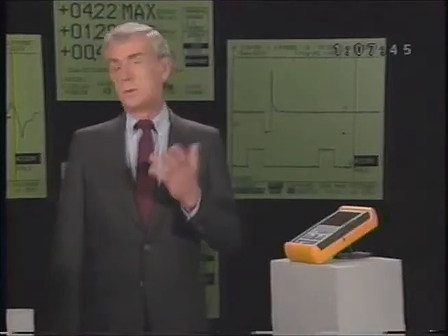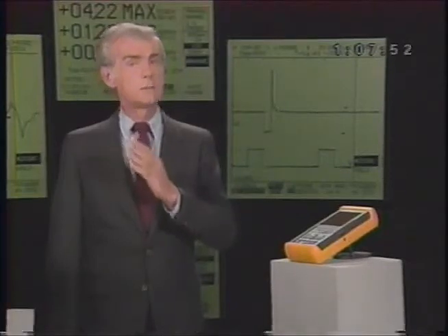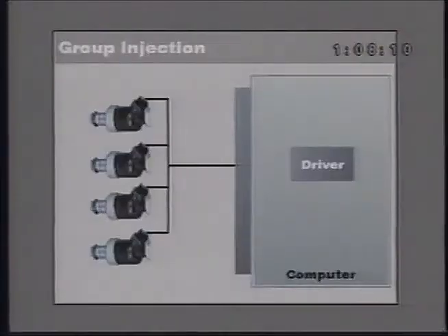Diagnosing injector waveforms is mostly a matter of experience and comparison. By viewing as many good injector waveforms as possible, bad ones become obvious immediately. One of the difficulties with diagnosing an injector based on its waveform is determining whether the problem's in the injector or the ECM driver transistor. Both can make the injector waveform look abnormal. How can you tell which is causing the problem?